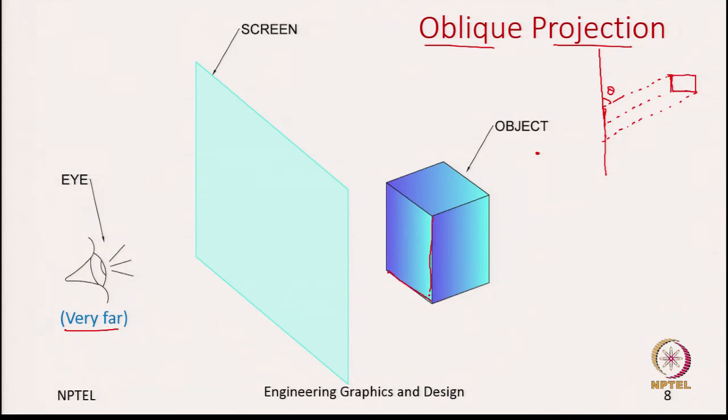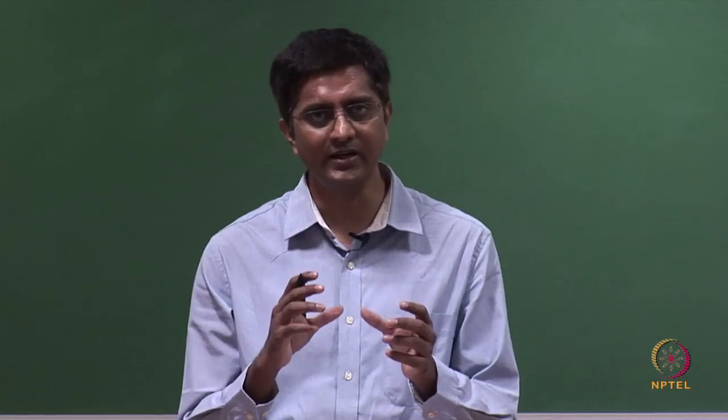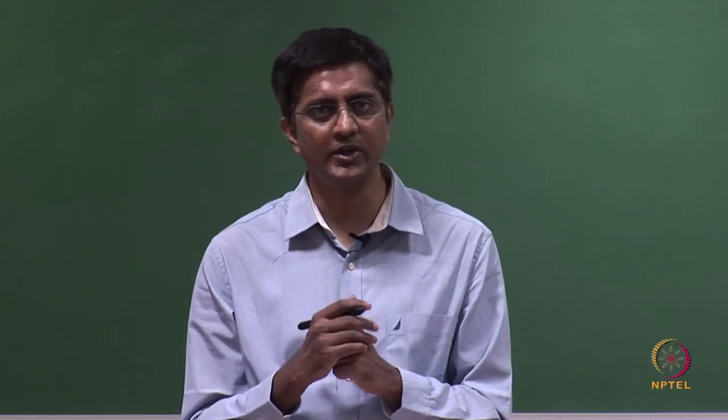Since both of them are parallel to the projection plane, you will be looking at the true length of this width and height. However, since the depth of the object is not parallel to the projection plane, that length is different. So, in the oblique views we are able to capture both the true width and height, however, the depth will be distorted.